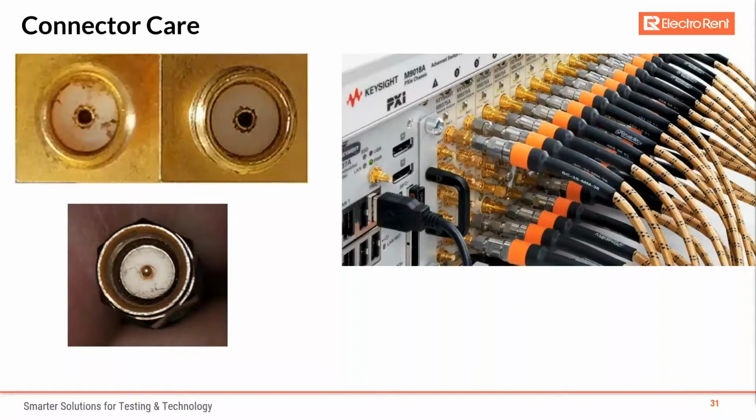In the example here, I'm showing you some pictures of some dirty or damaged coaxial connectors. And as you can see in this Keysight PXIe chassis, for example, with various network analyzers, connectors are used heavily. There are a lot of connectors, and as we move more into 5G, where you're going to have a lot more various ports coming out of your phone systems, for example, you'll definitely need to learn to keep these connectors in good shape and condition, and they will be more concise and restricted, as you can see here in the PXIe chassis.